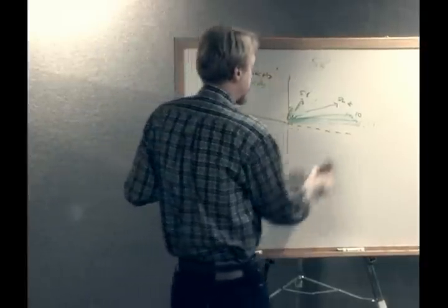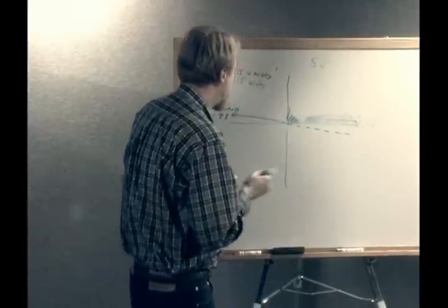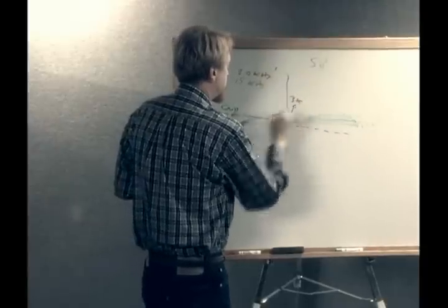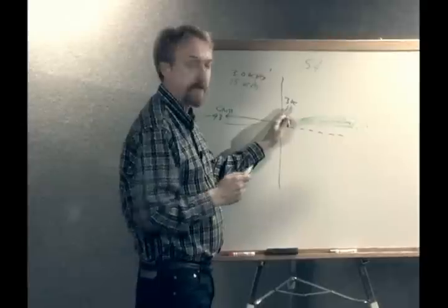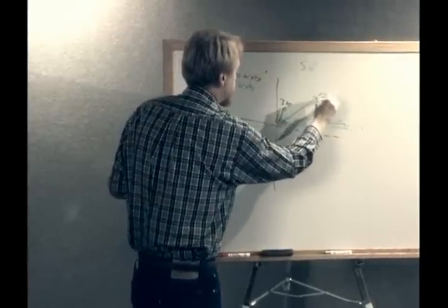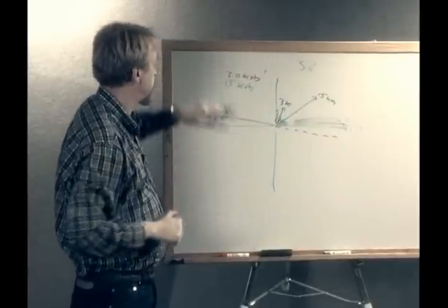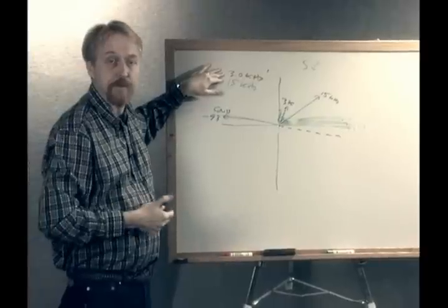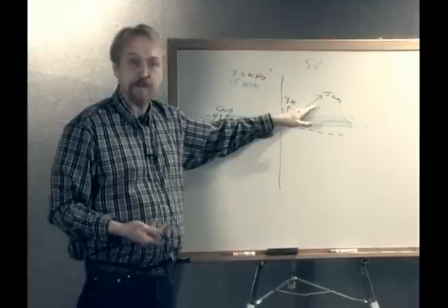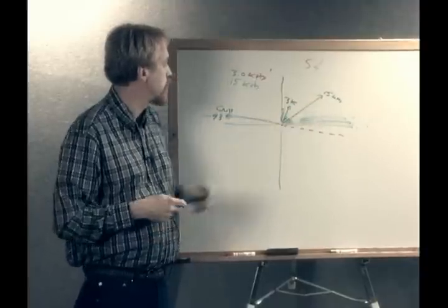So I'll give an example of that. If a nickel, for example, at 3 kilohertz has a fairly weak signal, and at 15 kilohertz the signal is much stronger, the microprocessor can look at both channels of information and select the strongest signal, which in this case would be 15 kilohertz, and then report that signal to the operator in the form of a VDI number and an audio response.